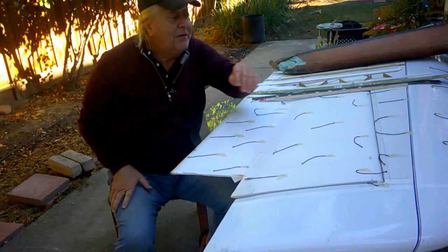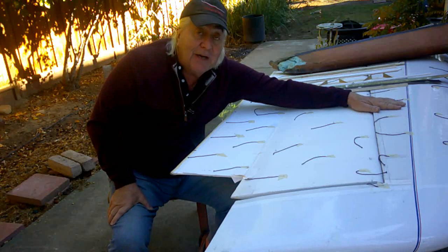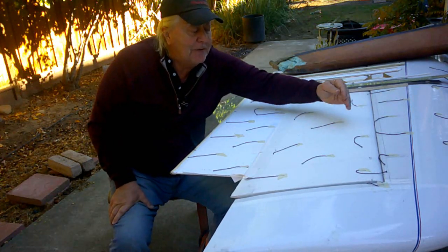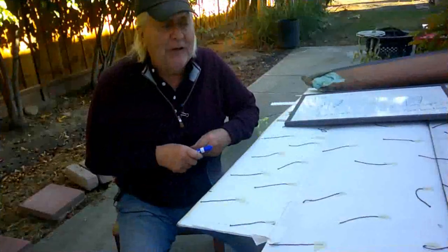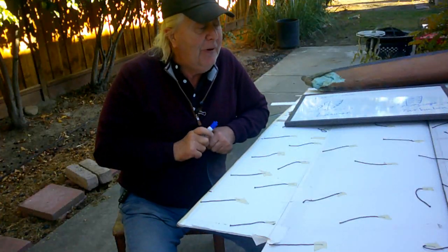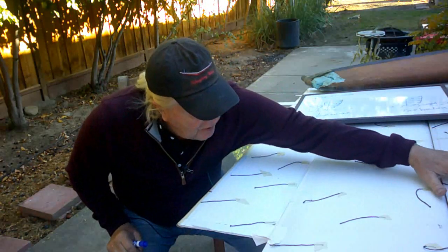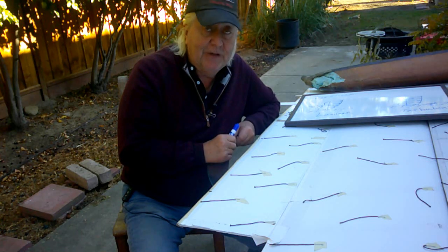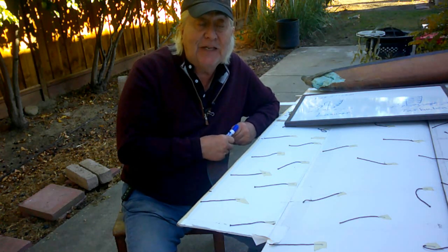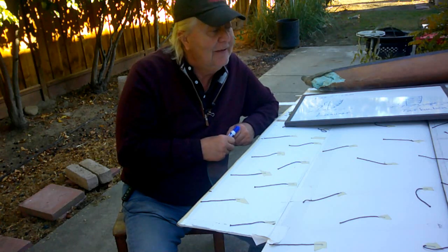So we deal with that by turbulating. We can deal with that by turbulating the boundary layer, putting trip strips on here to add energy to the boundary layer. This airfoil at 400,000, you should be able to put a trip strip on it up here and trip the flow and create turbulent boundary layer and keep it attached. Well, I've done that. I've done that in the most recent testing yesterday.